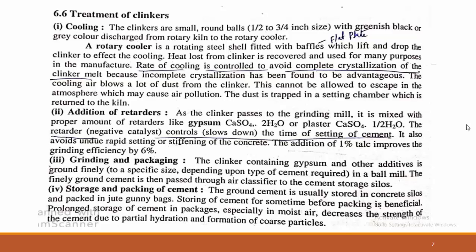These clinkers are cooled first. The rotary cooler is a rotating shell fitted with flat plates which lift and drop the clinkers to effect the cooling. Once the clinker is formed, cooling should take place. The rate of cooling is controlled to avoid the complete crystallization of the clinker.